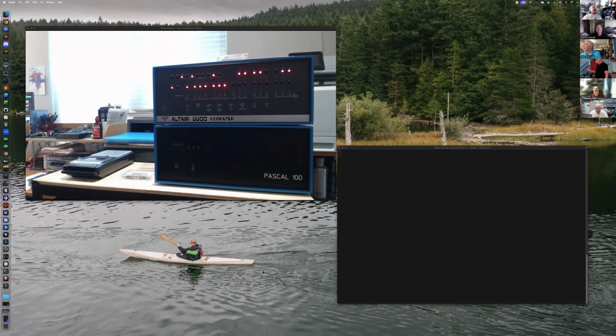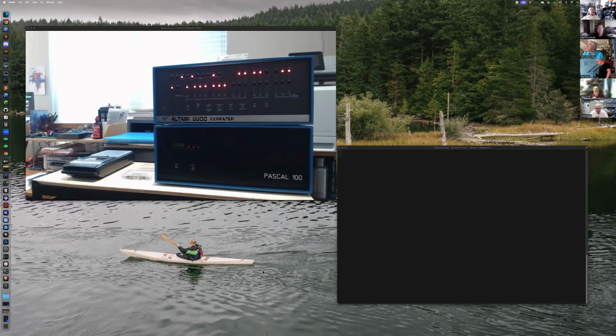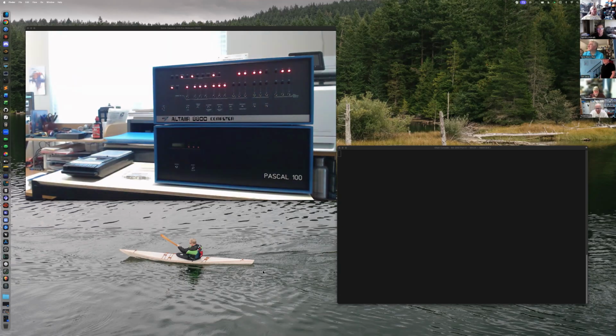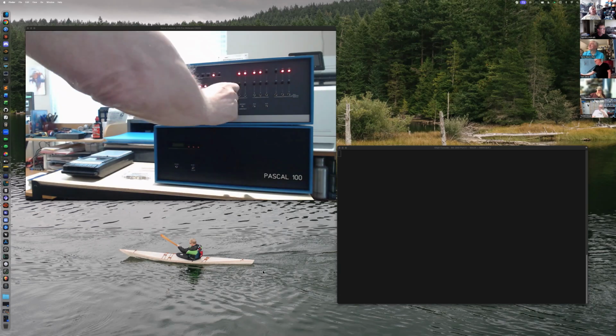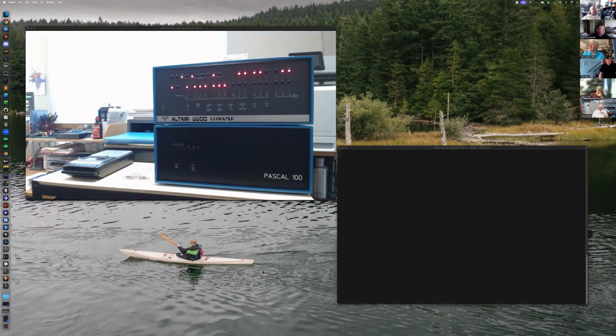Yeah. So anyway, let's go through it again. So this, yes, the multi-boot loader, standard Altair software, nothing special except it runs at FE00. Like I said, when you do an examine, you can see F3 is the first instruction. And then you use the top 8 switches to tell it what port the cassette is on and what port the console is on. I always forget which: the top 4 bits are the console, or the bottom 4 bits are the cassette, or the other way around. But anyway, if we set 12 and 8 and 9 up and everything else down, that tells it it's an ACR on port 6 and 7 with the console on SIO port 0 at hex 10 and 11.